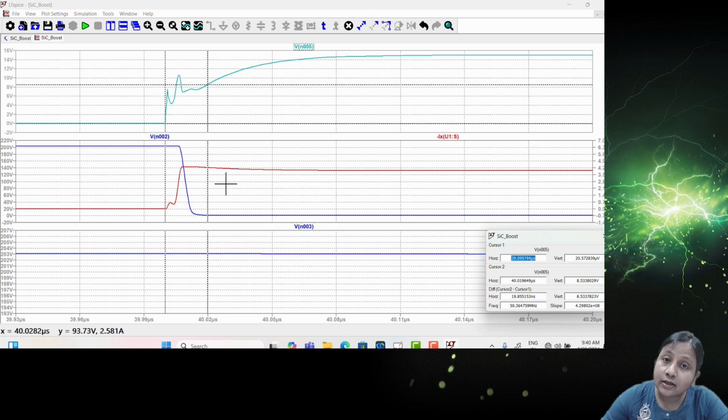Now you can use a similar type of window to understand the switching transient. This is not possible to understand in ideal simulation software. It is possible in LTspice because we are considering the actual switch, and you will get the actual kind of transient which will be visible in practical experimentation. So you can calculate the losses and then check them against the analysis, because in the analysis we will get some losses during turn on and turn off time, whether it is matching or not.